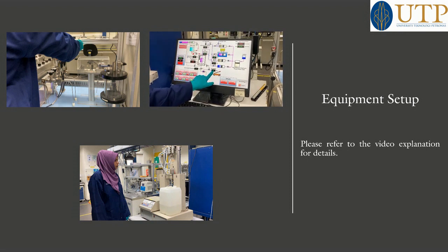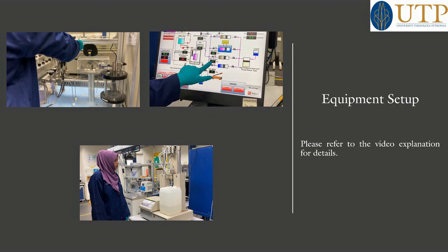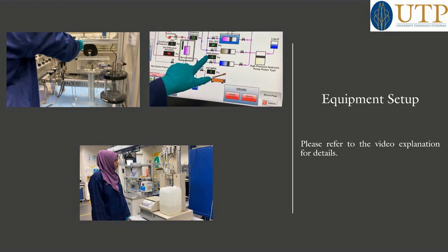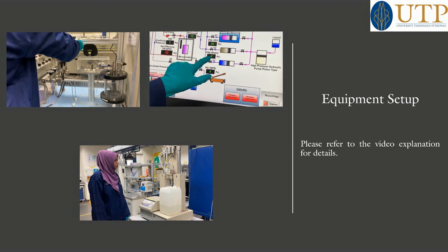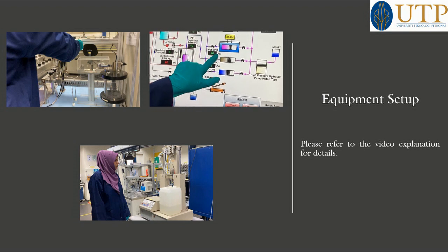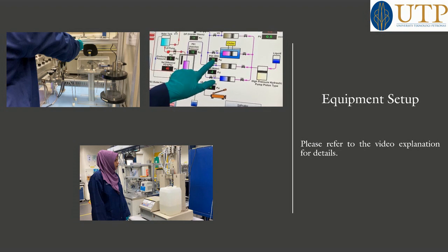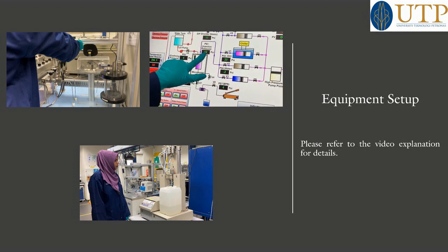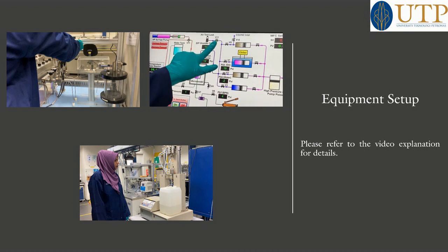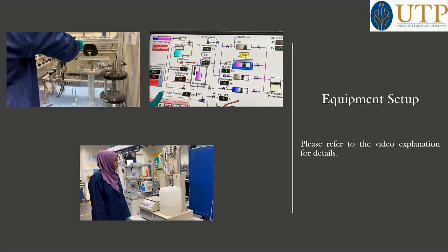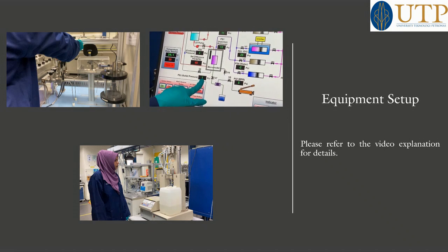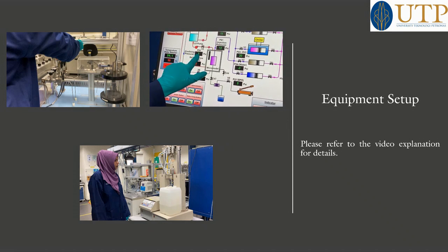So now my BPR pressure is 4, the pressure inside the water cylinder is -2, the pressure inside the oil cylinder is 20, my injection pressure is 12, my DP inside is 11, my outlet pressure is only 1, and the confining pressure is 3.